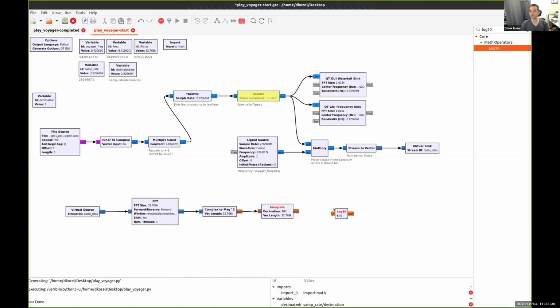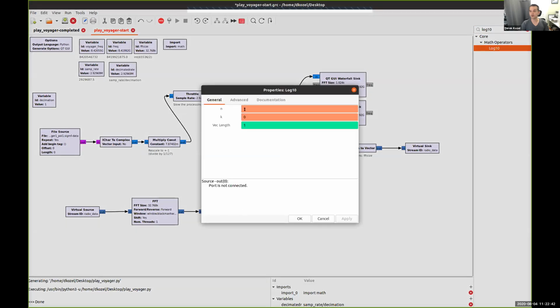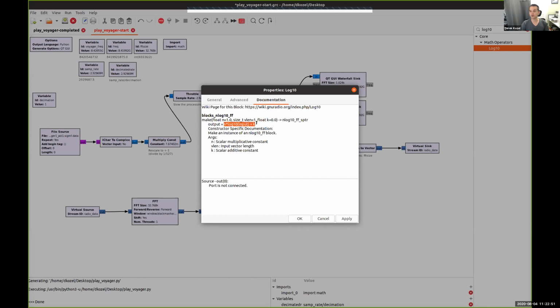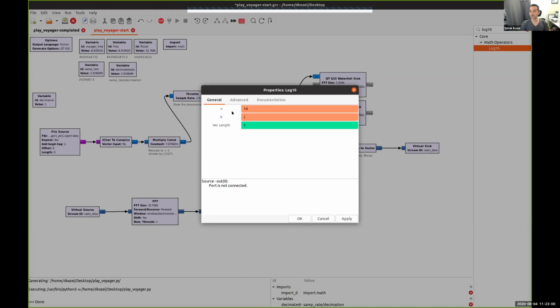Then we want to do the logarithm option. And the values we're going to use here is we're doing a 10 log 10. So 10 times log 10. I think the documentation, yeah, thankfully has a little bit of useful information here. And I have negative 30 in the flow graph there. It doesn't matter whether we put that in or not. I'll do it for consistency's sake. The reason it doesn't matter again is because we really only care about just putting it onto a log scale in decibels rather than putting it specifically into decibels milliwatt, which is where the negative 30 comes from.